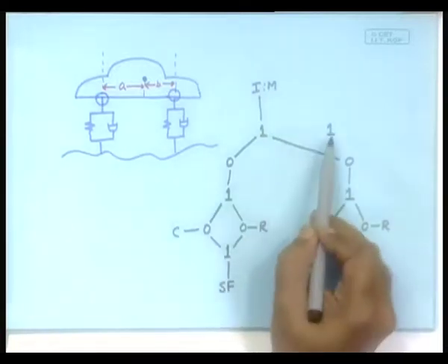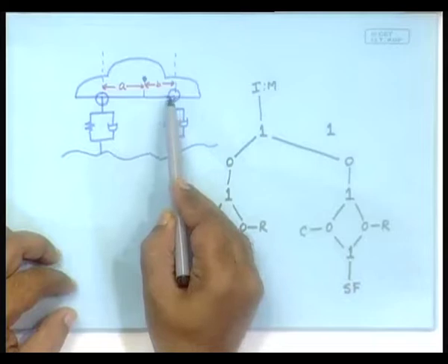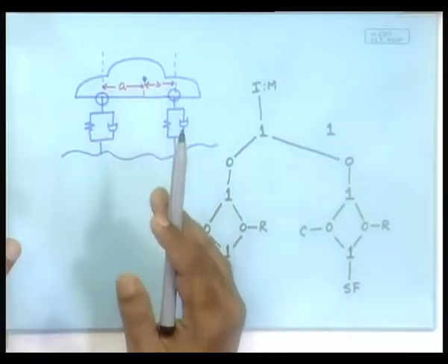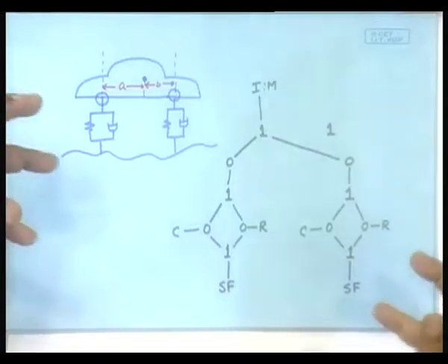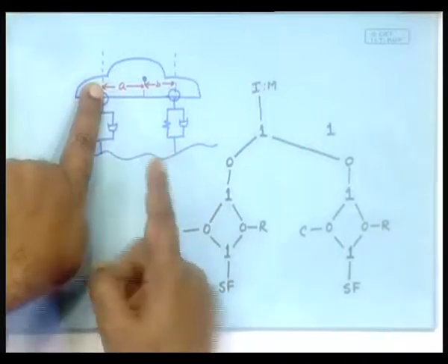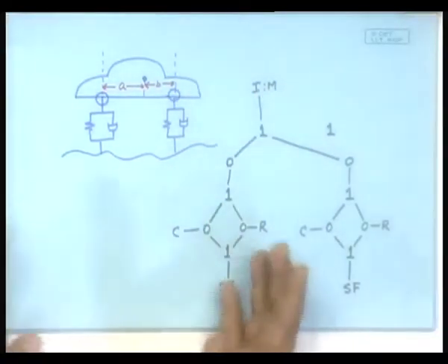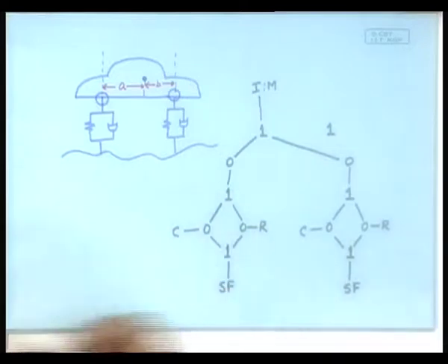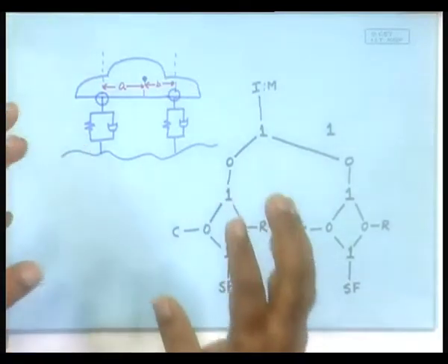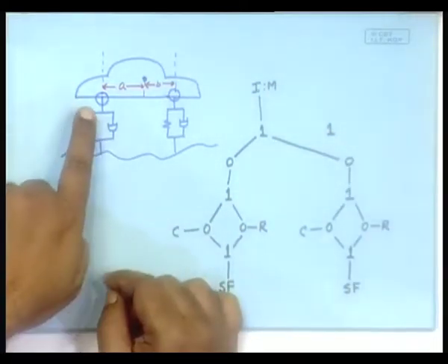Now, this is related to the rocking motion. Suppose you have applied a force here, and you have applied another force here, what creates the rocking motion? No, not the difference. Yes, it is a moment. So, the force applied times A will be the moment, the force applied times B will be the moment, and so the torque felt by this CG will be, yes, the moment.